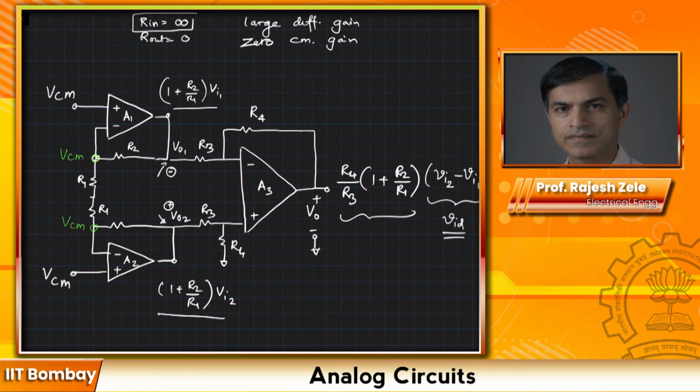Now comes the interesting point. Earlier, we had a ground connection over here, and what that did is it caused a common mode current of VCM divided by R1 to flow through this circuit like this. VCM divided by R1, and that current totally flew through this ground connection that we had. Then you would have 2 VCM divided by R1, and everything else is the same as what we discussed. So that common mode gets amplified at VO1 and VO2. As soon as I remove this connection, something changes, and I hope you can observe that.